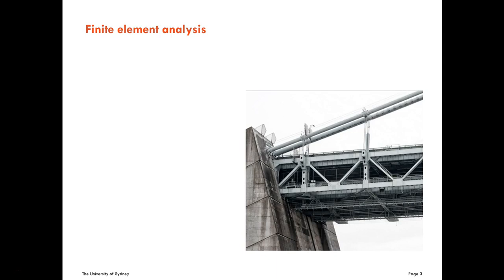Okay, let's look at the detail of the structure. So it has many elements. I'm talking about the structural elements. Some of these elements will be simplified by finite elements. For example, this flexural member is going to be replaced by a beam element, an element with two nodes. And this element is going to have an element stiffness matrix.